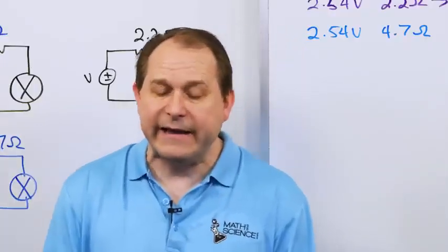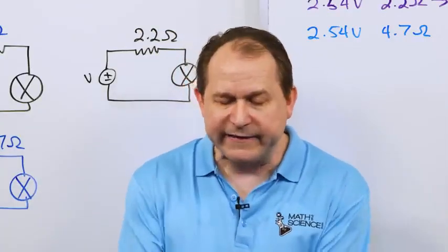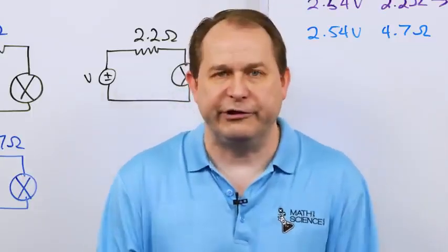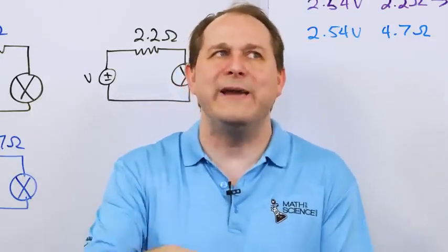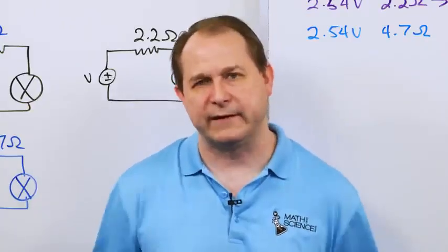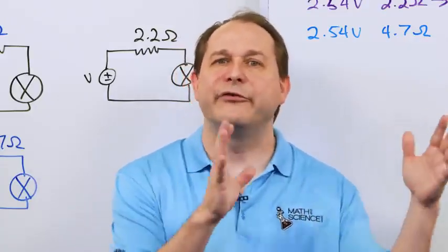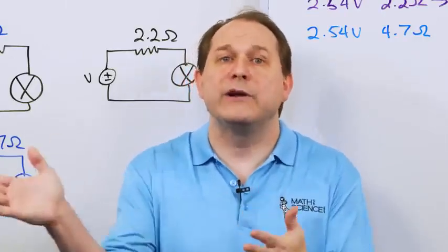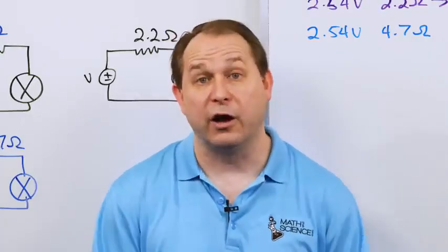So what happened in that case is I designed the circuit, so to speak, to operate at a certain amount of current that this light bulb is designed to take. But when a short circuit happens elsewhere in the circuit, the current surges because you're bypassing all the resistance in the circuit. You put the resistor in place in order to make the current the right level for this light bulb. When you circumvent it, the current spikes and it burns out the light bulb. Now in a house or a car, a surge of current can cause a fire. So that's why you have the circuit breakers on the outside of your home, or if it's in a car, you have fuses that are designed to burn out if there's ever a short circuit. So short circuits are dangerous because the current surges and can actually cause a fire.